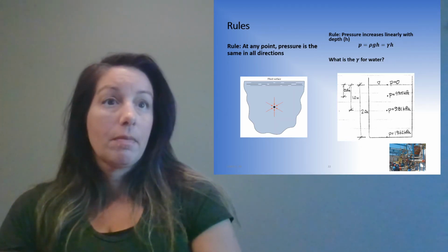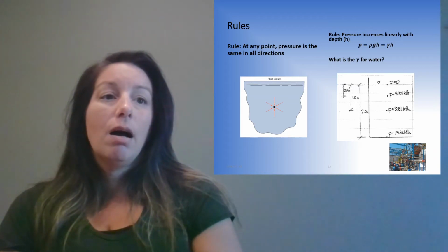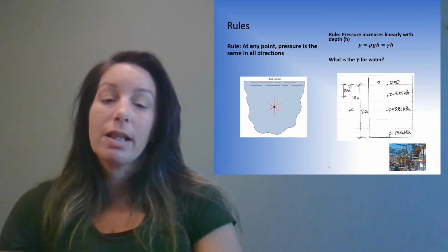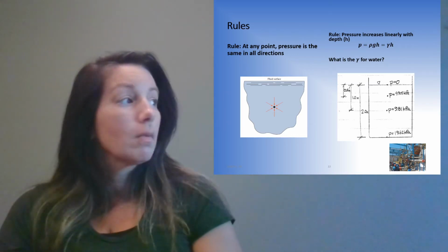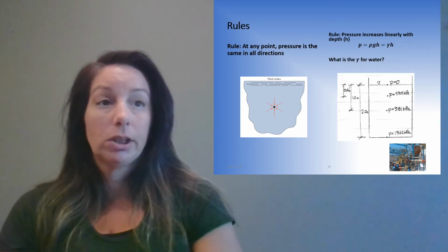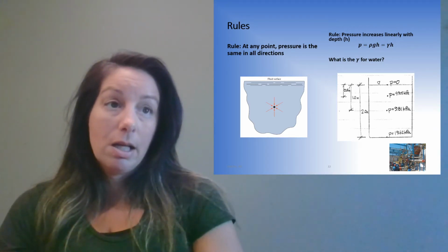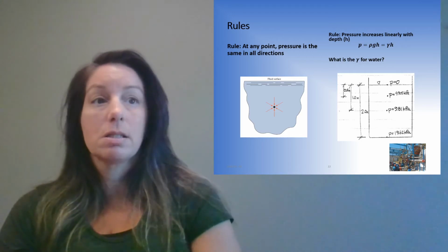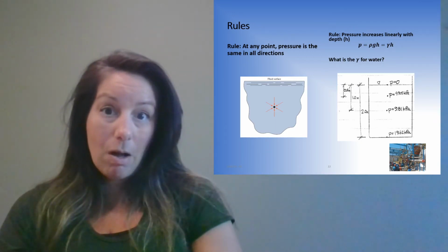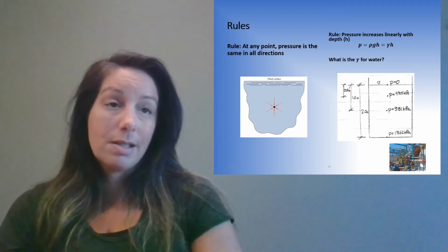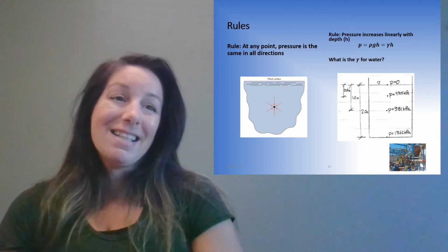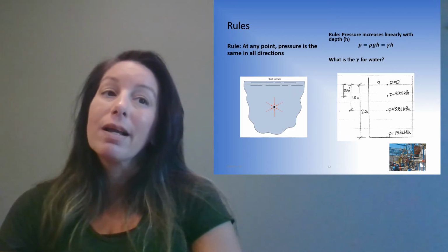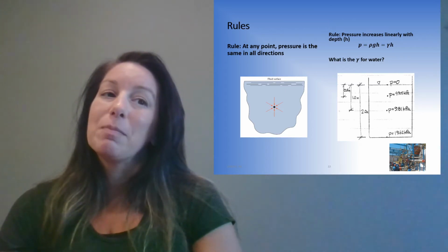Uniform liquid. Okay. So what is the gamma for water? It's telling you there. So the pressure at the surface of the water is 0. There's no pressure acting on it. Atmospheric pressure, but we'll get into that later on. It's generally 0. If you go down half a meter within the water column, this is probably fresh water, not salt water, at a certain temperature. We'll get into it again. It's 4.905 kPa, and at 1 meter it's 9.81 kPa, and at 2 it's 19.61 kPa.